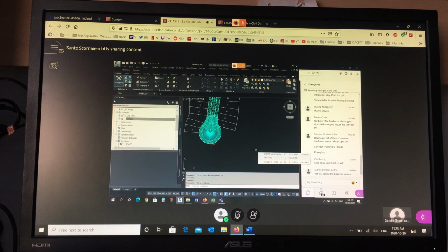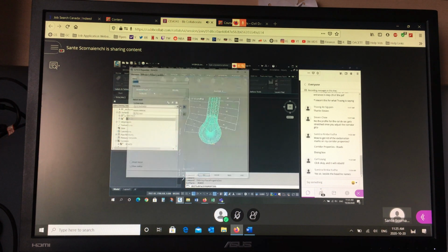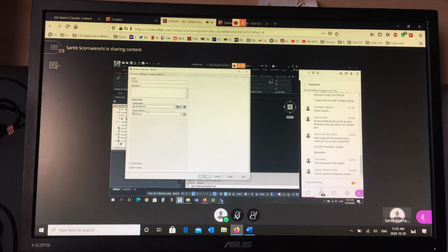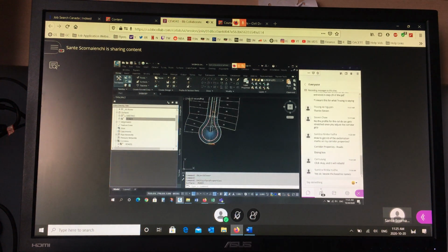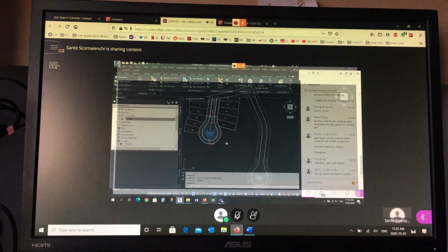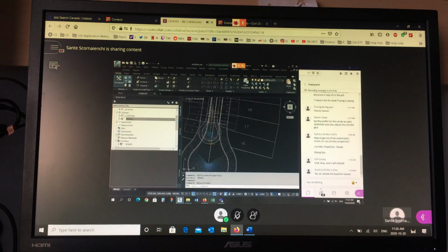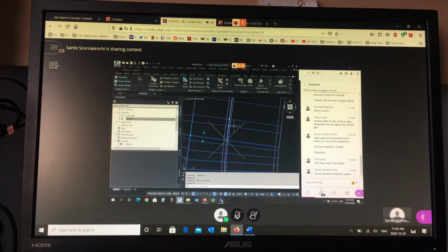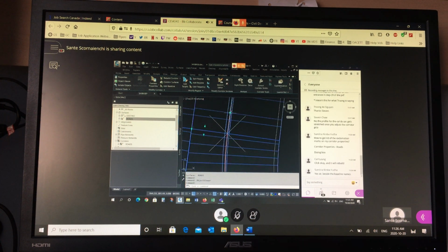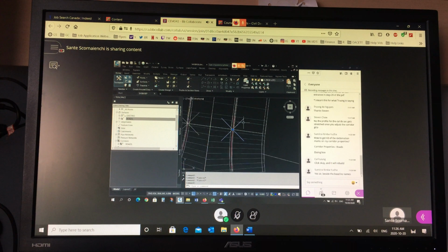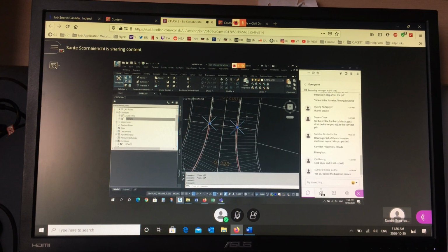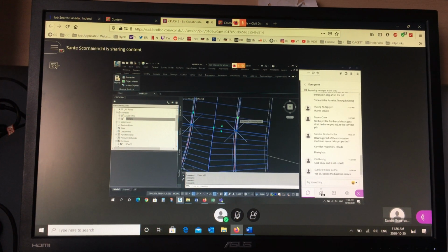So I'm going to get rid of the surface, object viewer. I'm going to get rid of the surface, no display. Let me look at the corridor in 3D, and you'll see exactly the problem. Object viewer. Spikes are actually coming from the corridor model, and the reason for it is, you remember, the start of the range for the horizontal alignment of the gutter is before the profile. So the profile design starts here and ends here. But at the beginning and at the end, the horizontal alignment starts a little bit before and goes a little bit past. In those areas, there's a zero elevation, right?